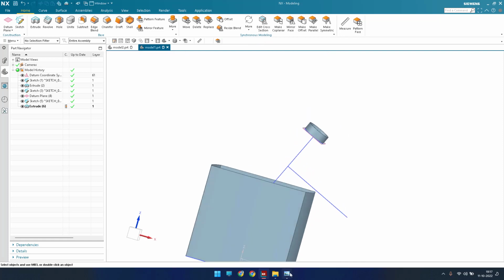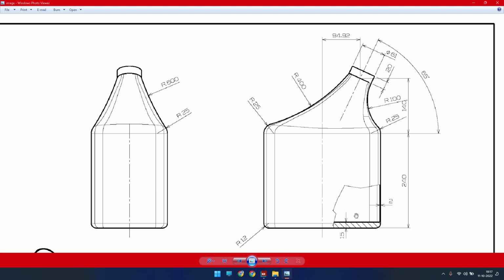So now you can see here the base rectangle we have, that we have received, and we also got this cylinder. So now our main part comes. So we need to connect between these two by using through curve mesh. So before going into through curve mesh, we have to make the arcs we have here, 400 mm and 110 mm, and also this is 600 mm. So these four arcs we have to create.